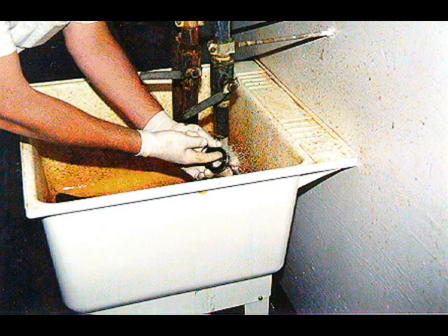If one of the faces is dropped on the floor, do not install it. The interfaces must be very clean. If a face should become soiled, it should be washed with water only. Used faces can be reused if they are returned to the manufacturer for refinishing. Whether this is cost-effective will depend on the size of the seal.